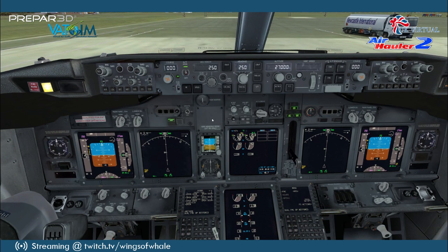So there we go. I've just engaged reverse thrusters, and auto throttle is disengaged, so I just flick it back on. So just keep an eye that you haven't accidentally removed auto throttle. It does give you a warning, so you should notice anyway.